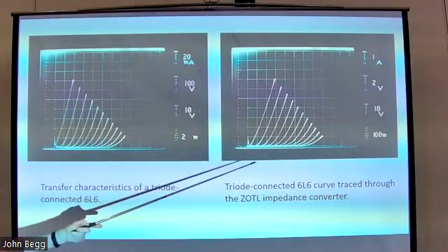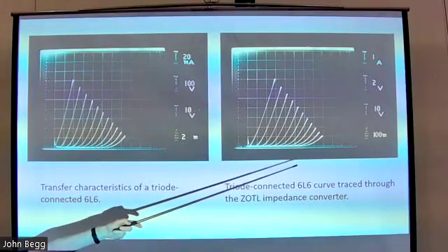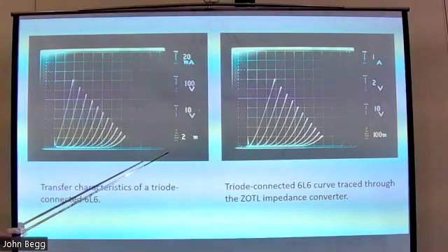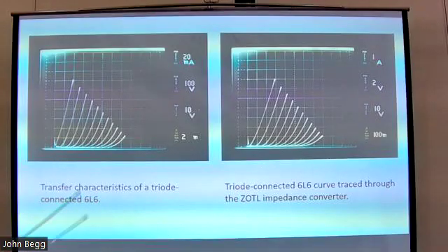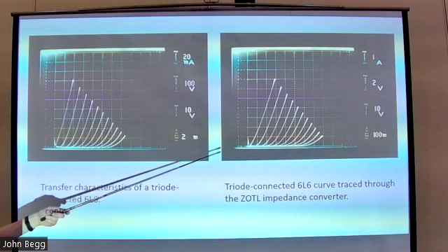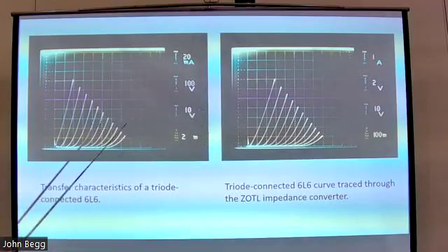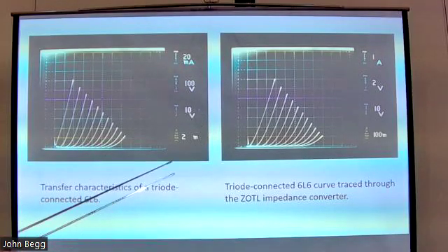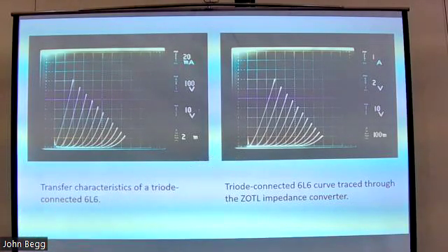Note the change in the transconductance. Huge. 2 here. I think this is millisiemens now, I think that's a term they use. 100 millisiemens. I mean, that's a huge change. So this device, if you look at this as a device, boy, isn't that great for driving the speaker? Look at all the current I get, and I don't need that much voltage. So that's super. The steps are the same, 10 volts per step. So anyway, next.